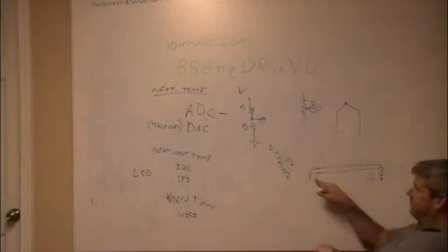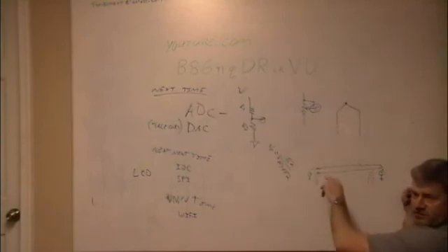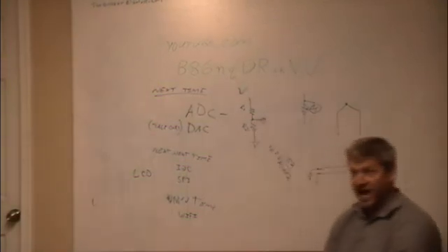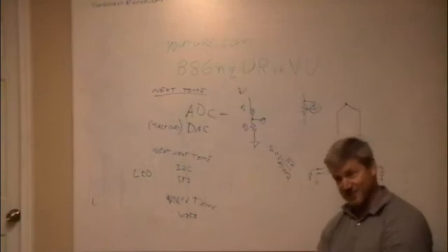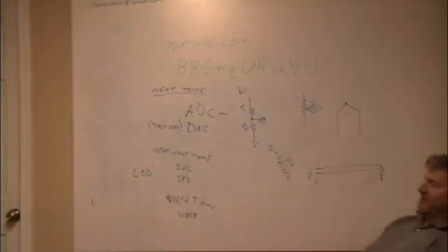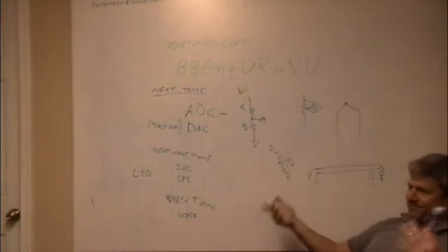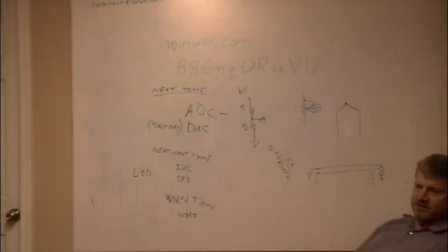So that means that the voltage I see here changes. So they used to use an ice bath, because if you've got a bath of melting ice, it's exactly 0 degrees C, right? So it's called an ice reference, and Analog Devices makes them, TI makes them, all your major semiconductor people who deal with analog stuff make them.